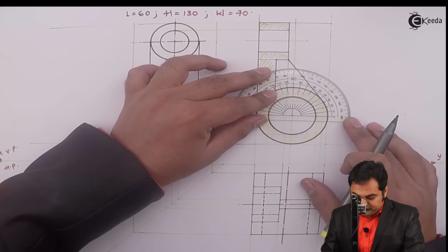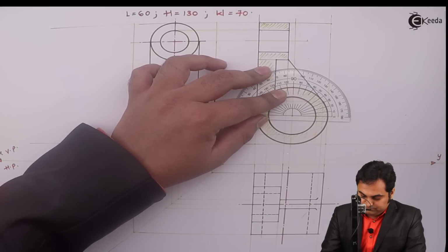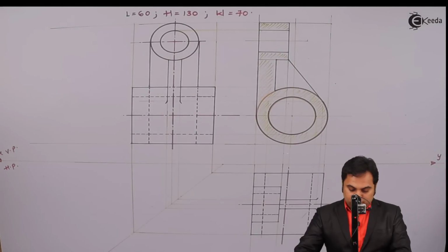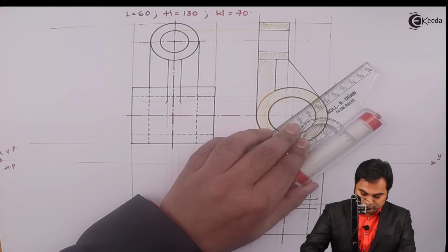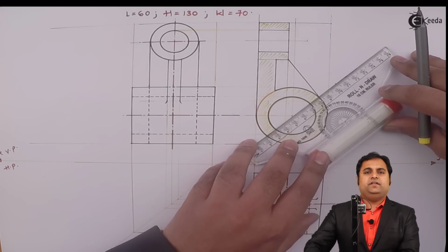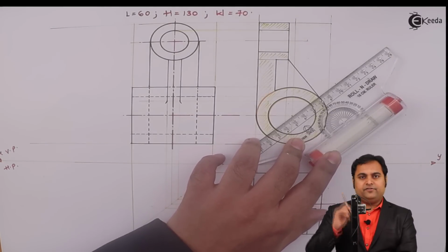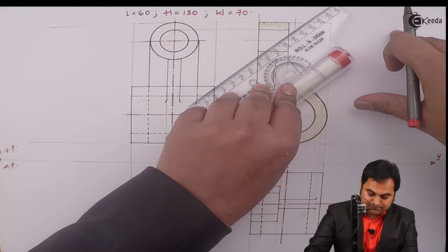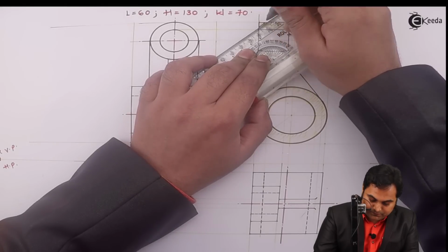So with respect to any point inside the drawing, I am taking 45 degree angle, joining a light line through this point. Then parallel to this light line, I will be drawing the section lines. Hence remember, section lines are medium dark lines, so they should be lighter than the outline. Here I am using black color for the dark line, red will be for medium dark line or the sectioning lines. So I am starting the section here. These lines should be equally spaced, inclined at 45 degree.